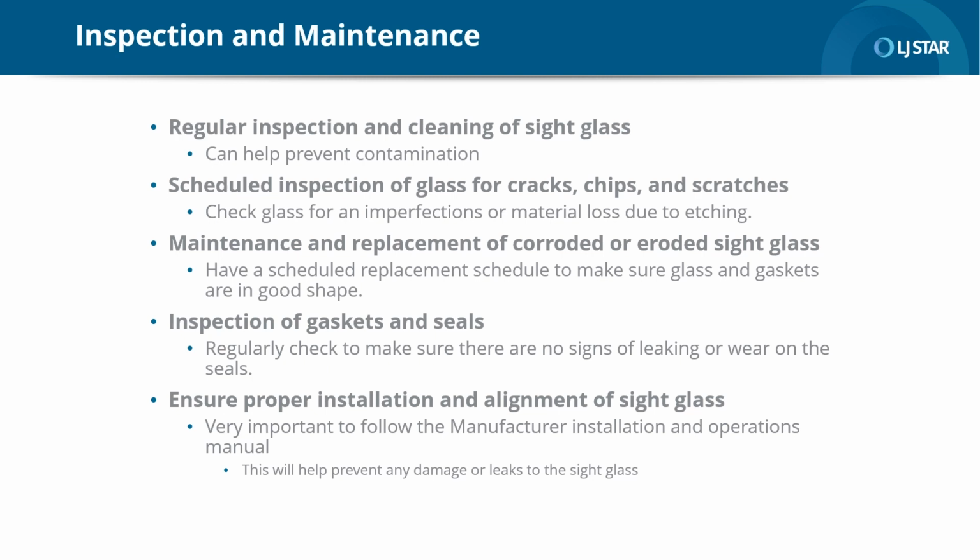And then you want to tighten that pattern at a partial load, and you want to do that multiple times, increasing every time until you hit the full load, so that way you keep a nice, even, parallel mounting surface and not cause the glass to break or the seal to not seat right. That way you make sure that everything is how it should be. And all of these notes are going to be found in the installation manuals.